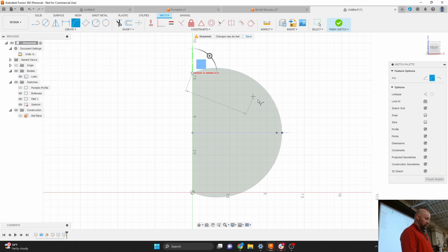And after I make this 3-point arc, I'm going to come around and take a look and see where you guys are at. So again, I get free geometry here, so this point already exists on here, and this point already exists, so I'm just snapping to both of these points. And then my third point in this 3-point arc is going to be right out here.